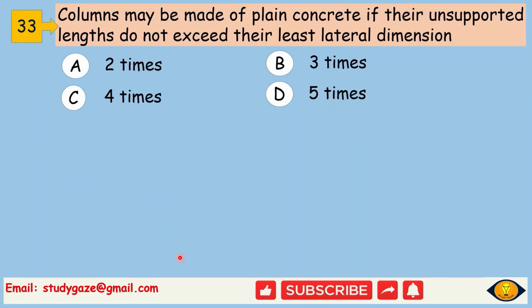Columns may be made of plain concrete if their unsupported length does not exceed their lateral dimension by how many times? So the correct option is 4 times. Sometimes 3 times is also a correct option, because when we make a pedestal using plain concrete, the pedestal limit is 3 times. Okay.